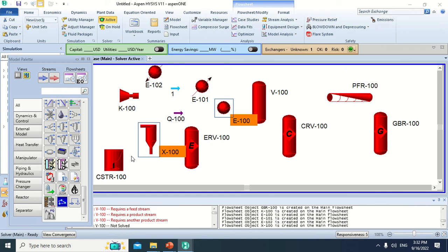The upper part of the cyclone is larger than the lower part, so big particles have a lot of inertia when they are in the rotation path and cannot go through the narrow carrier path of the cyclone. These particles hit the cyclone wall and are thrown towards the outlet of the chamber and out of the system.